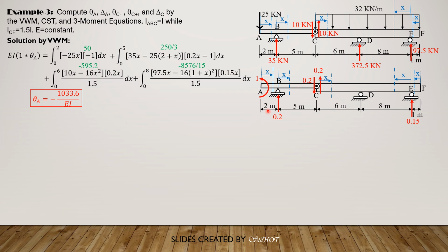Next, we draw another beam, same beam, loaded with a unit virtual load at A, which is upward, to make it positive. We assume that the deflection is positive. Then let's compute the reaction here. The reaction here should be downward. So downward reaction times 5 equals 1 times 7. So 7 divided by 5 is 1.4.